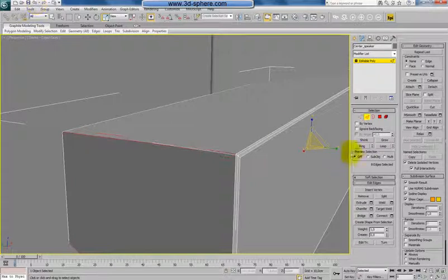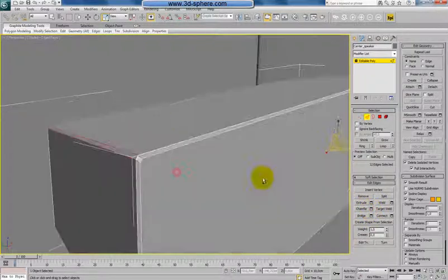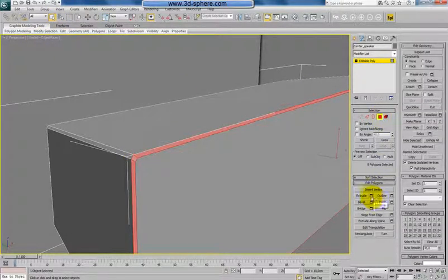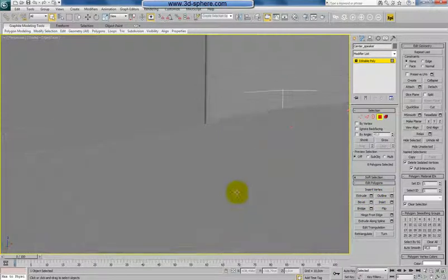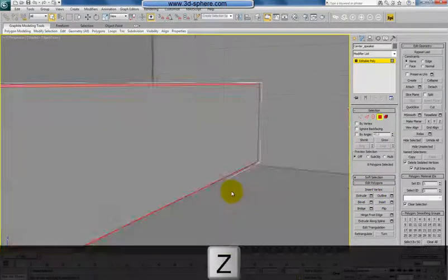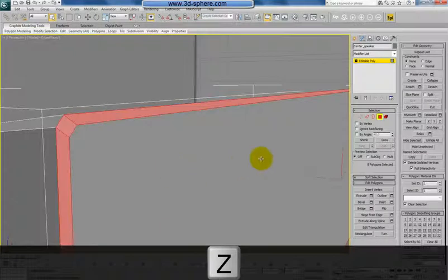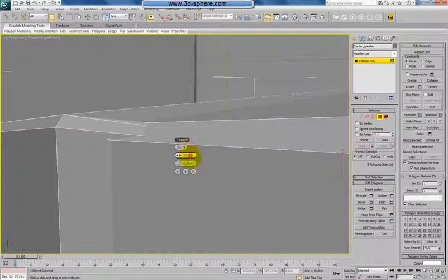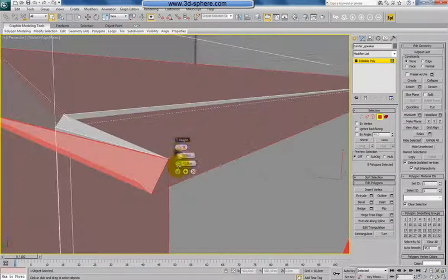Oops. Hit the loop button. I forgot about that. Yeah, now it's fine. Now select this edge here, the small one. Ring that, control poly. Now I will do here a small, let's say, the small border, the metallic border which was there between the materials. And for that I will use the bevel tool. So let's go to local normal, make it 0.